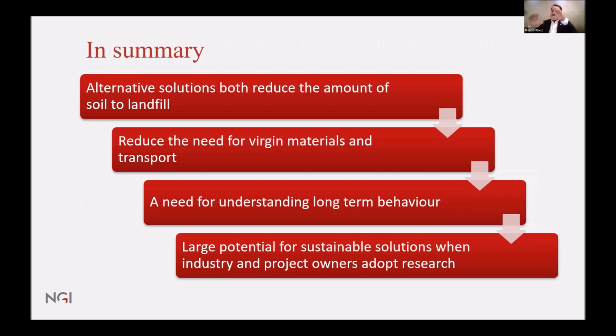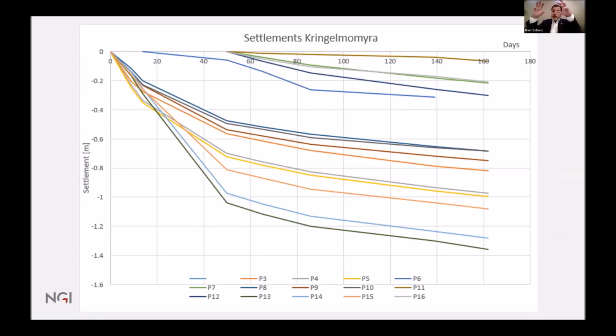Very, very nice. So the idea is to build a strong embankment that will settle evenly? Yes. So we've had an additional load, and then when we take that load away, the ground has been pre-consolidated to a higher load than it will be subjected to in the permanent phase. So there's still an element of creep. So the longer we can leave the surcharge fill, the better, yes.